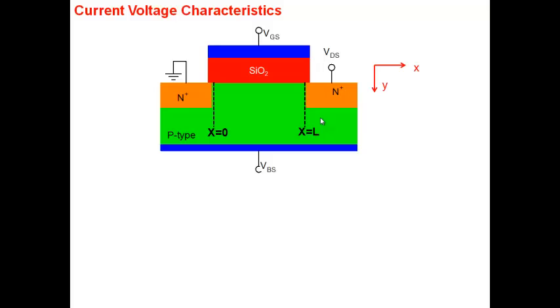All right, so let's start with the current voltage characteristics. For our N-channel MOSFET, the current is primarily electron current. The hole current is simply not there or negligible. What we are going to assume, and as part of a homework problem you can easily show, is that when you are above threshold and looking at the linear region or saturation region, the current can be modeled as primarily drift. Of course there'll be a diffusion component, but as I said, it's primarily drift, which means that the drift component is much larger than the diffusion component here.